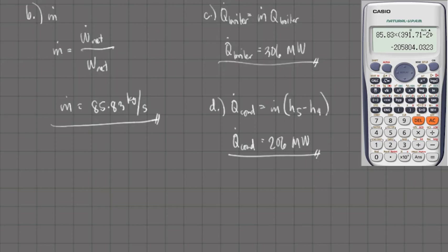We really cannot directly compare this Rankine cycle with reheat and superheat with that of the basic Rankine cycle. That's because the two cycles have different states of steam that is exiting the boiler. Also, the exiting pressure of the turbine must be optimized such that the state of the steam that is entering the condenser is either a saturated vapor or a saturated mixture. In our case, the stream that is exiting the second stage of the turbine is still a superheated steam, which still carries a significant amount of energy that is simply wasted by directly discharging it into the condenser.